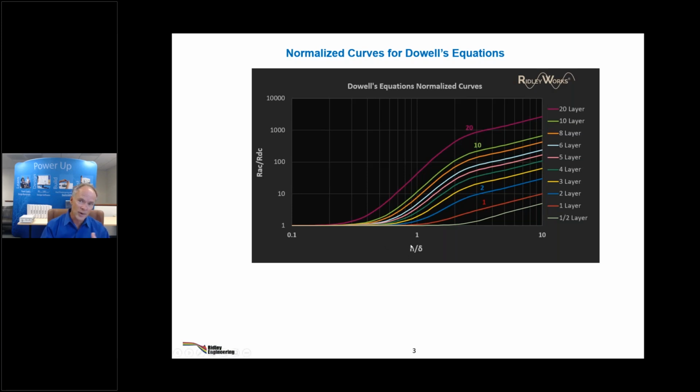So as you change the height of the winding, the curves are going to shift. And then on the left-hand side is the AC resistance with respect to the DC resistance. And of course, as you make a winding thicker, you're going to change the DC resistance, you're going to change that ratio, but you're also going to change the height relative to the skin depth. So we've actually got a triple normalization in these curves. And that is the source of people these days not knowing quite how to use them. And I don't think any of this is taught anymore.